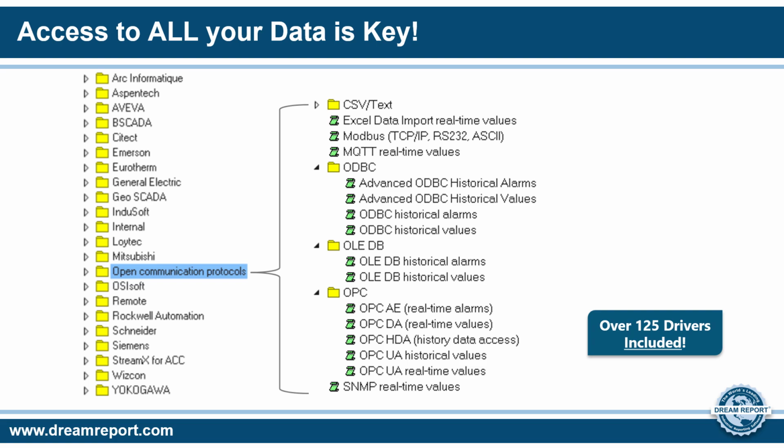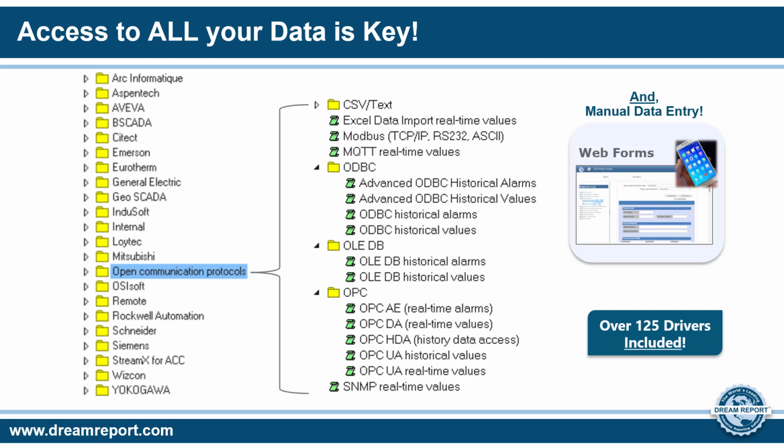The industrial protocols are typically built using toolkits from the different automation vendors and partners we work with. So everything from OSI PI and PI Event Frames, Proficy Historian from GE, Rockwell FactoryTalk Historian and VTScada. You name it, we have connectors for HMI products, for historians, alarm and event loggers, and directly to PLCs. Additionally, we support manual data entry and then report on it along with all the other process data.